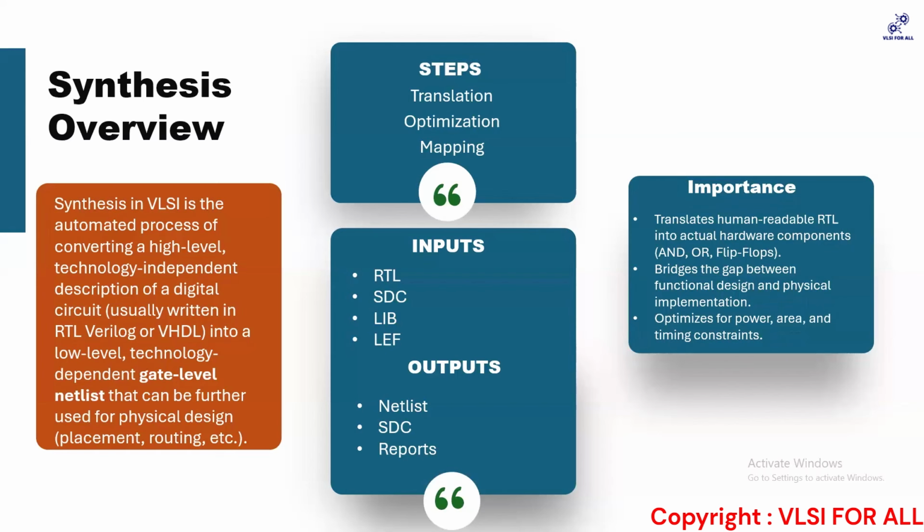Okay, and the way it is important is how I'm going to optimize it. This is the main importance of synthesis, optimization. Otherwise, it could have been done in a very simple format. You could have just grabbed the RTL, converted it into the gates, and it is done. But the main intention behind synthesis is complete optimization strategies. As and when we proceed further, I'll explain the various strategies involved in it. And the main intention is to meet your PPA target, which is power, performance, and area.